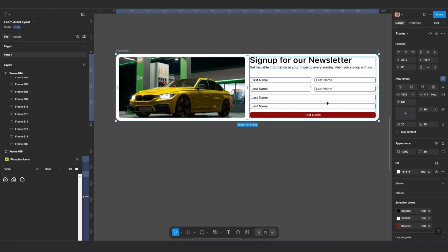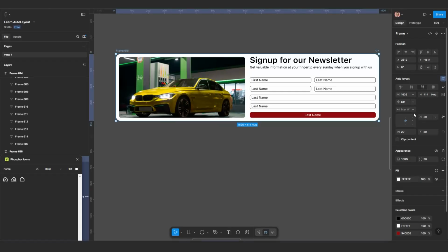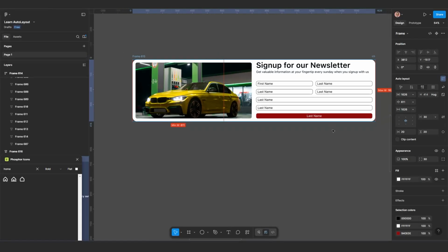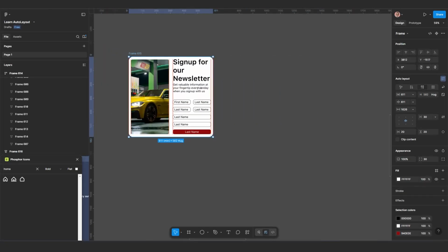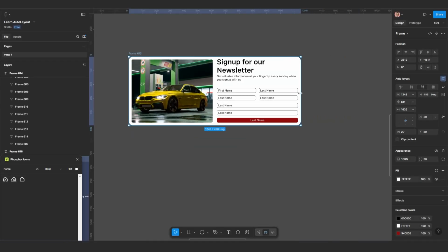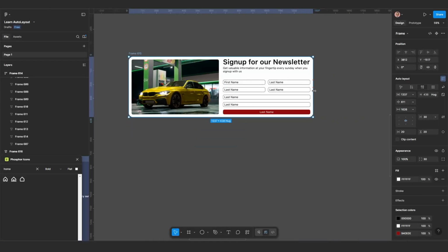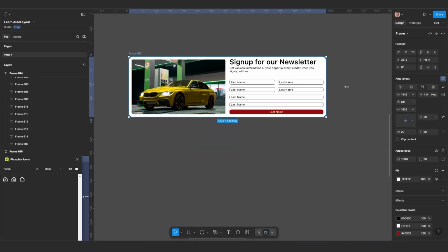So what we can do here is to select and say, instead of minimum, we'll click here and say add maximum width. That means whenever you get here, don't extend beyond this level, set to current width. So what we just did is that we can resize these guys in between here and here, no longer going beyond this level anymore.